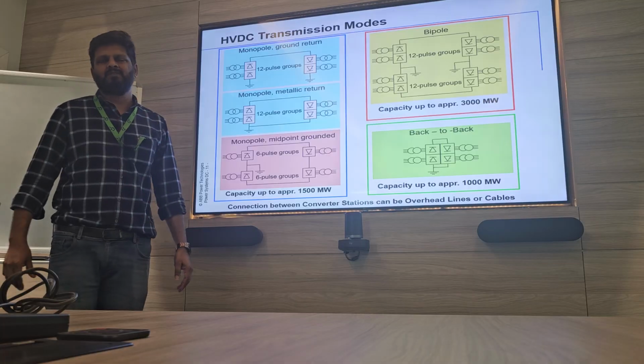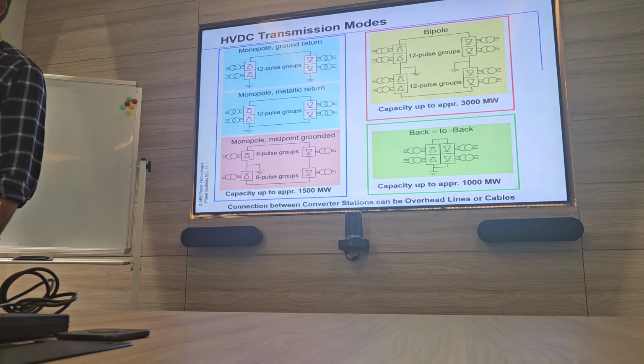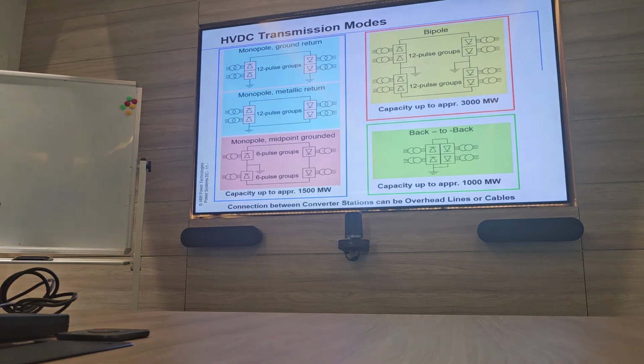So they are going to synchronize the network without any large power transfer. They are going to connect Jordan and Saudi Arabia, for example, but they don't have the capacity to move other power. If we propose connecting KSA to Jordan, which are asynchronous to each other with different frequencies, and we introduce back to back, we are going to limit ourselves to a certain power, not similar to the other options.